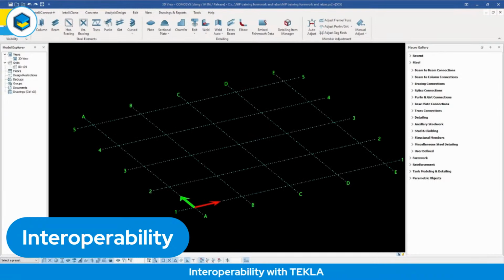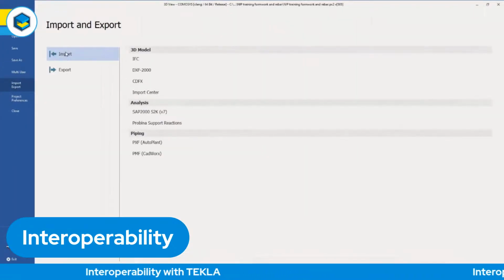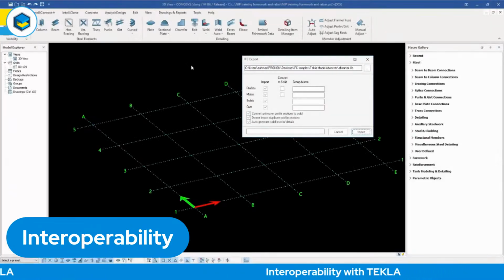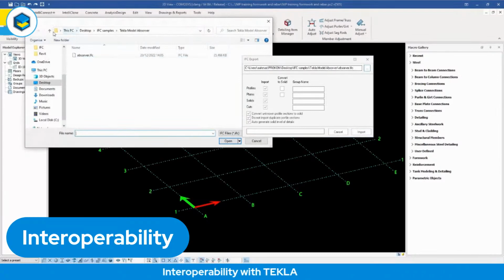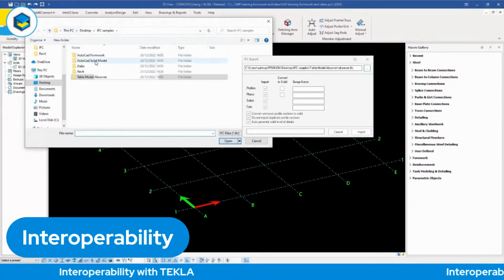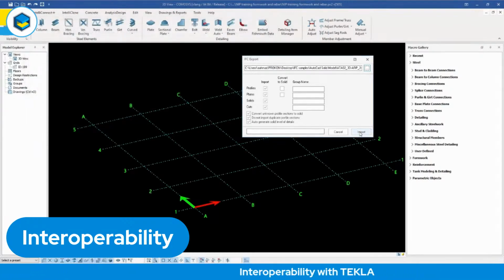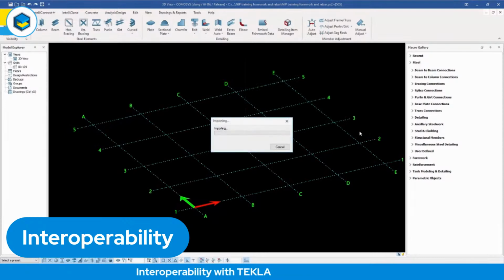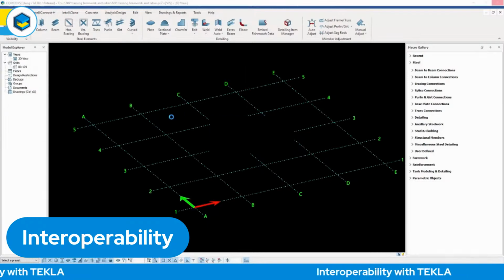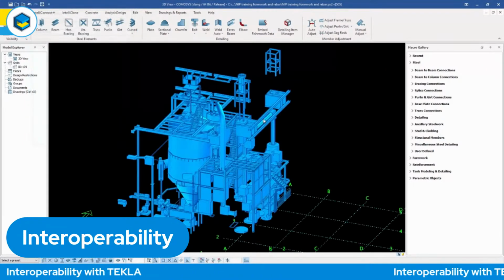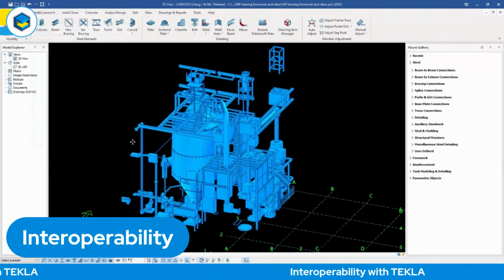I want to do one more example of actual equipment. So you will require in certain cases to import equipment, for example, in the form of IFC files. So I have an example over here. It's this one, imported from an AutoCAD file. Let me just press that and press the import button. It starts reading the file, and then it gives us a map. Once again, as always, it takes us to this material map and the profile map. I can just say confirm. And once it's done, you can see the results on the screen.